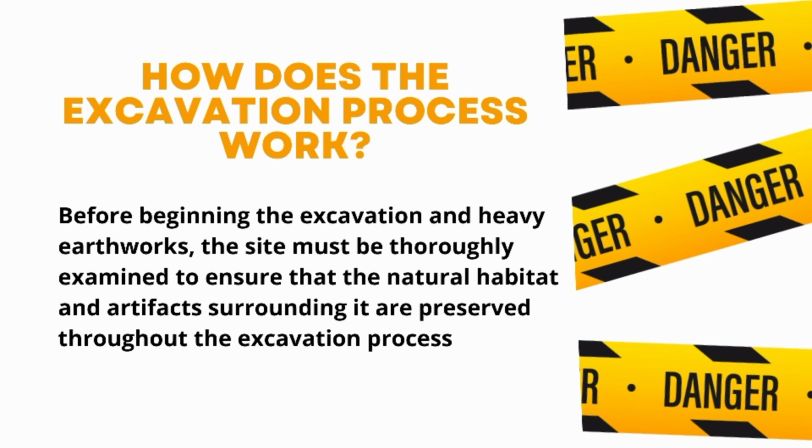As an engineer, one must first evaluate any excavation near or below a structure's footing, including retaining walls. One must ensure that other structures near the excavation site are not harmed by vibration or concussion during the work. Consider the need for special precautions if hospitals or other buildings with sensitive shock and vibration equipment are nearby. And review and, if necessary, revise controls to maintain a work environment that does not have risks to health and safety.